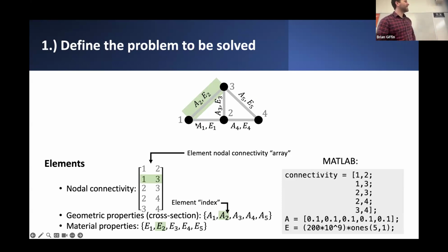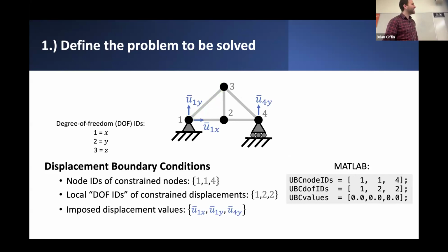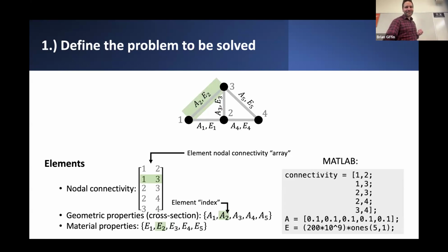So it depends how you're actually going about prescribing boundary conditions. If we're prescribing boundary conditions to the nodes directly, which maybe segues into this next slide, those constraints are imposed on the nodes, but they don't necessarily pertain to the elements. The elements can be rearranged or reoriented with different connectivity.